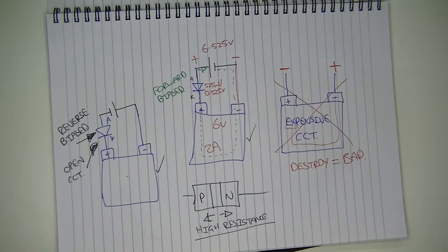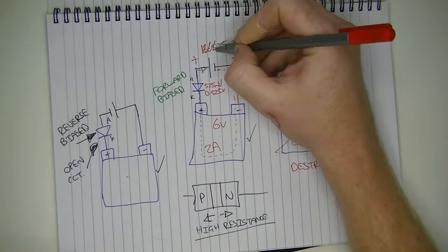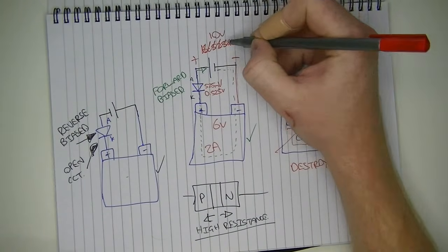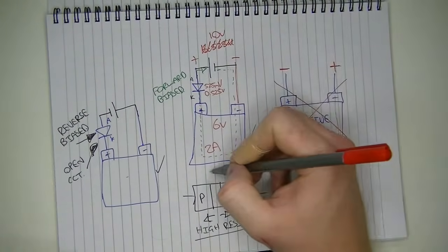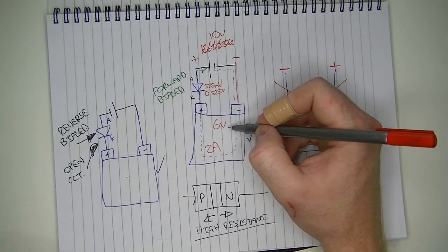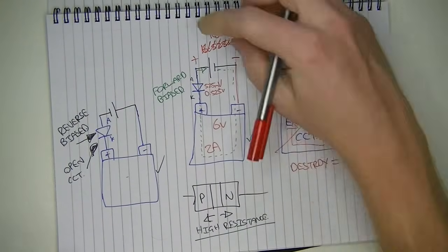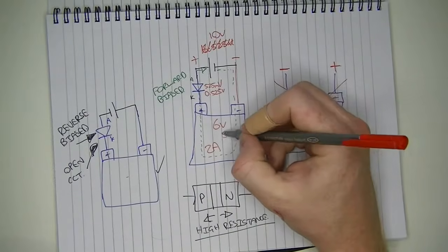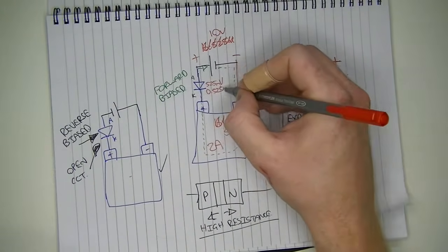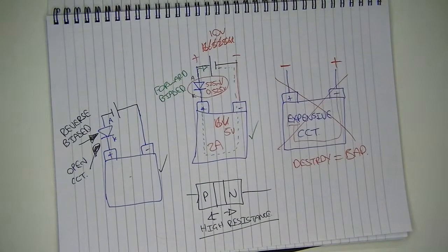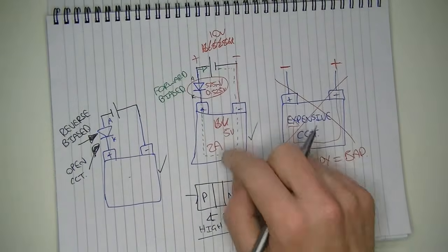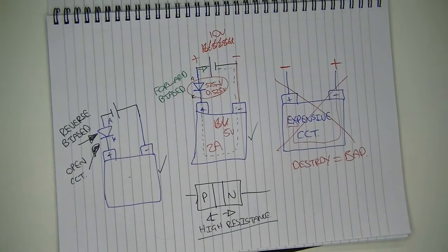Normally, this isn't such a big deal because you might be using maybe, I don't know, let's say a 10 volt power supply. And in your circuit, you probably would have a regulator. And that regulator might regulate that down to maybe 5 volts. So it really doesn't make much difference that this will be grabbing 525 millivolts because your circuit would normally have a regulator in it anyway.